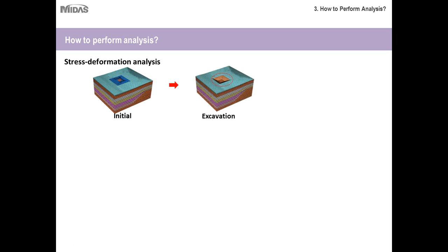Then you will start the excavation. So we take out the mesh components that are excavated. So now these stresses will be relieved here. There will be some sort of unloading because of removing of the earth. So you can see the stress distribution and deformation occurring.